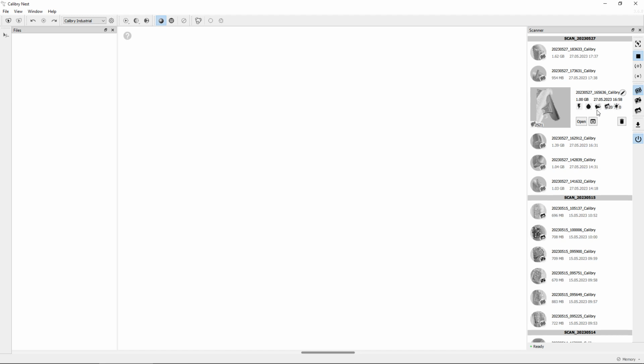I'm showing you some of the samples with Live 3D and without. This is the frequency of texture frames, how often we're going to make pictures of the object during scanning. These frames then can be used for texturizing the model. And the brightness, of course, we can change depending on the conditions in which we're scanning.